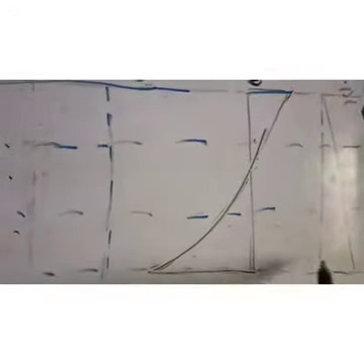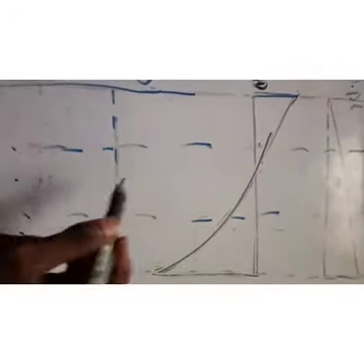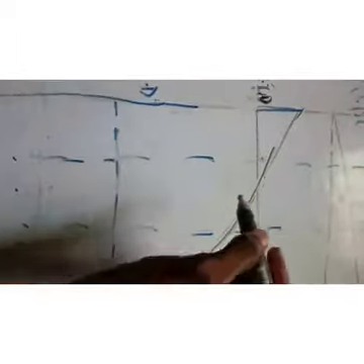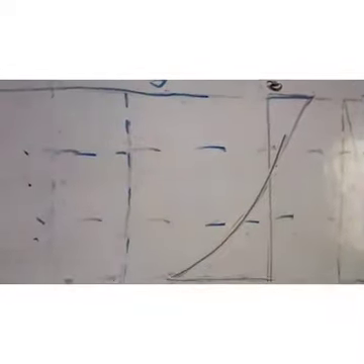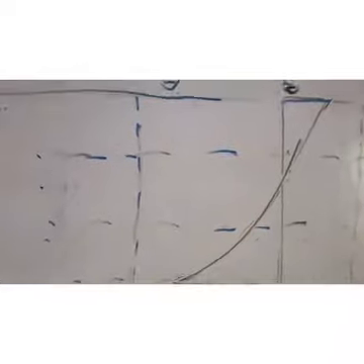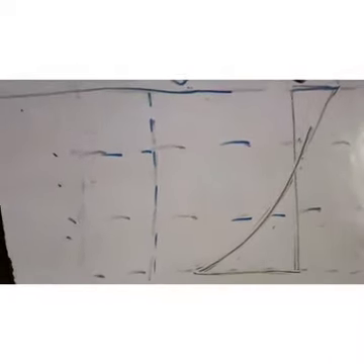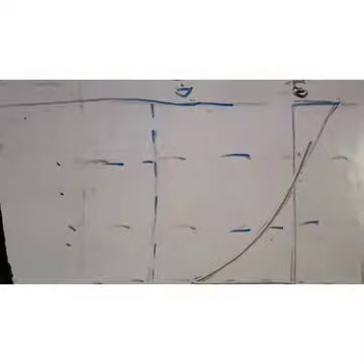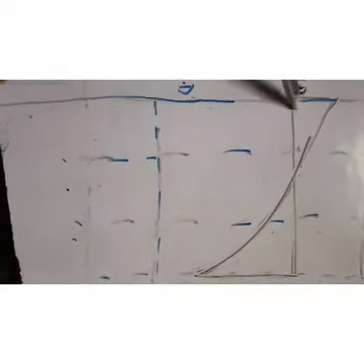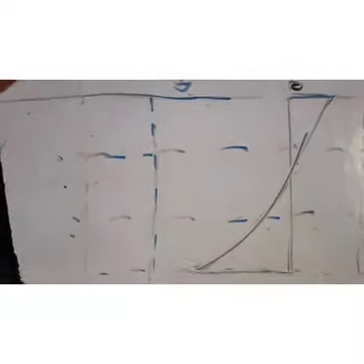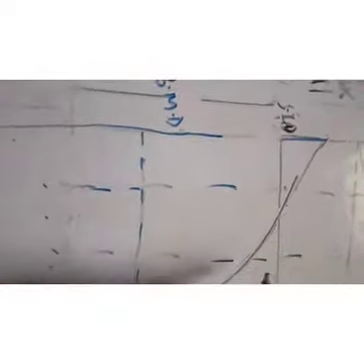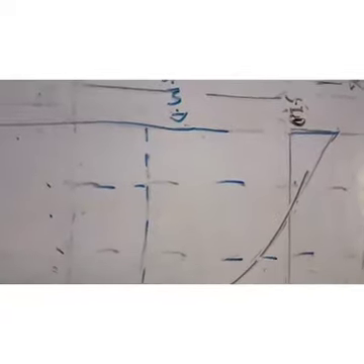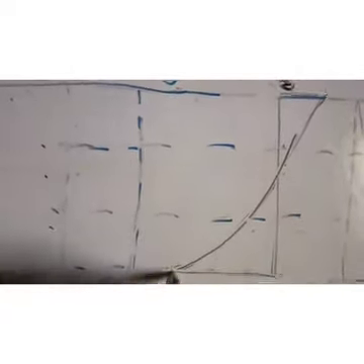Then when you draw it, you section it, and that is 0, here is 1, this is 2, and that is 3. So 0, 1, 2, 3. Now if you plot it from your table, the shear force at point 0 is 1. Then you take 1. Then the next one is 0.66. Next one is minus 0.3, and the last one is minus 2. See, here is minus 2.